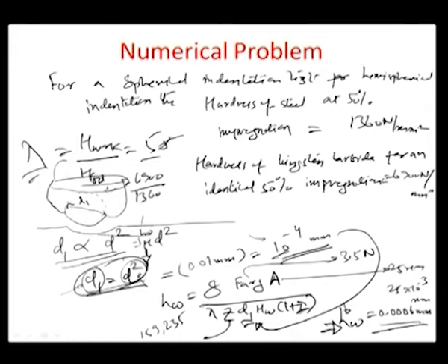So one thing that I would be very carefully looking at is the magnitude of the indentation that is happening on a surface. It is only about close to 0.6 microns, okay. So it is not even 1 micron. Which means that the surface finish of such a process is expected to be very, very high, okay.